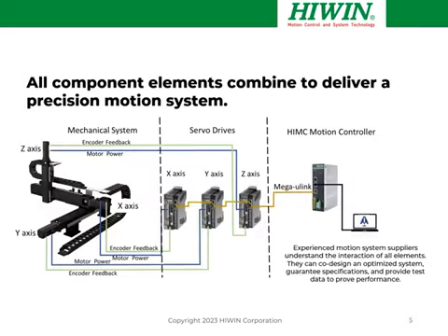When we talk about a motion system in this webinar, we're really referring to a complete positioning system that consists of a mechanical system or a mechatronic system with the structural mechanics plus some type of drive elements and some feedback elements, the servo drives, which are the electronics that power the system, and ultimately the motion controller, which will coordinate the motion of the various servo drives.